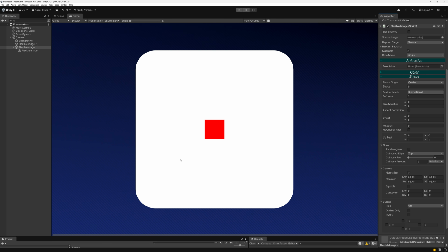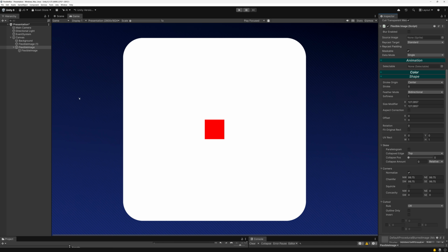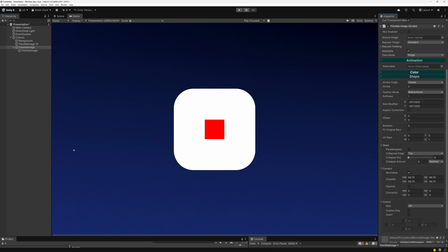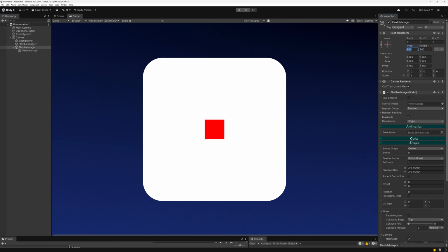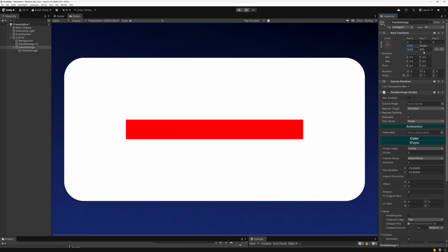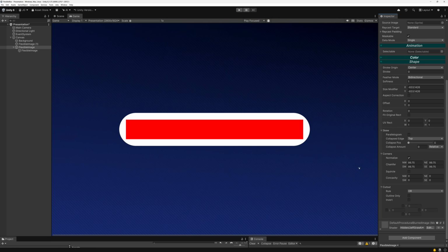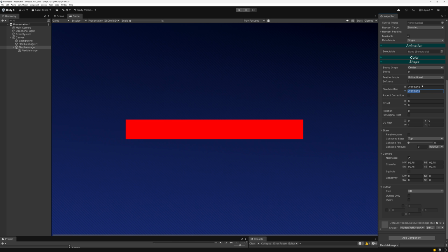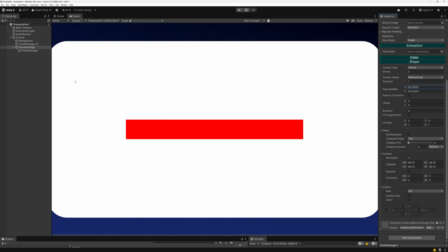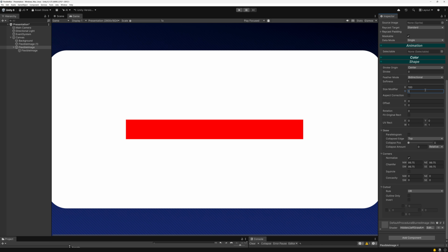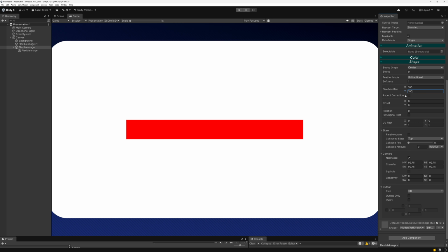So this could be useful when you want to position things with an offset, but not have the children offset, or when you want to do animation that doesn't affect children. We have this aspect correction toggle here, and all that means is if, say, for example, I had 1600 width and 800 height, and if I apply a size modifier, actually let's zero those out. If we apply a size modifier, we're growing by 100 units here, both horizontally and vertically.